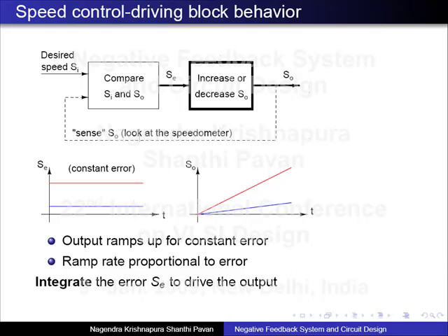Whatever you said about this feedback, I think in general, it's the concept of feedback, I believe. If you say there is this concept of negative feedback, what is the concept of positive feedback then? No, negative feedback means that you drive it in a direction where the error becomes smaller, right? You sense the error and you drive it in the opposite direction. My belief is the output with a negative feedback falls back.